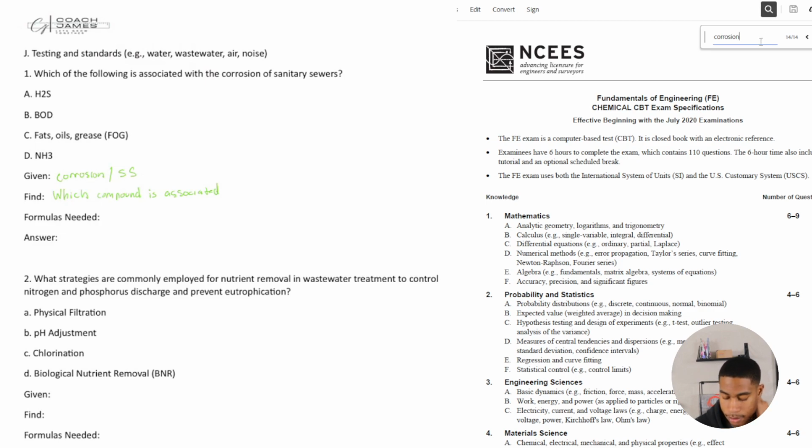Okay, so would it be H2S, BOD, fats, oils, greases, or NH3? Your answer is going to be H2S. Now I did make some notes for you here. So what is H2S? It's hydrogen sulfide, right? And it is often associated with the corrosion of sanitary sewers. So if you think of hydrogen sulfide, that is what corrodes sanitary sewers.